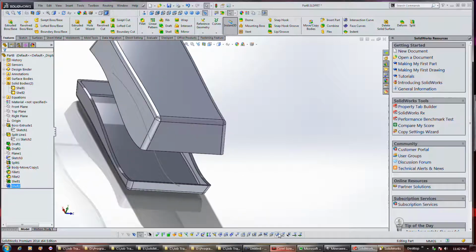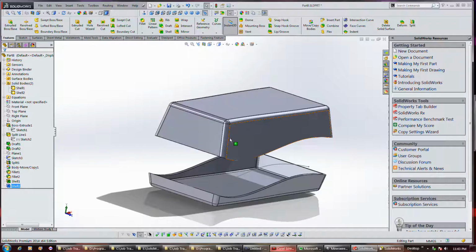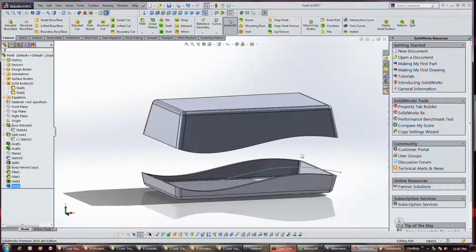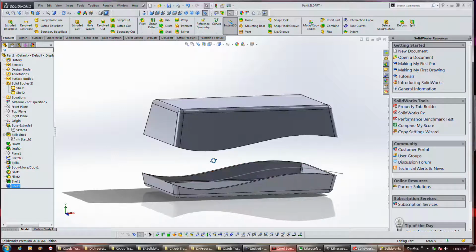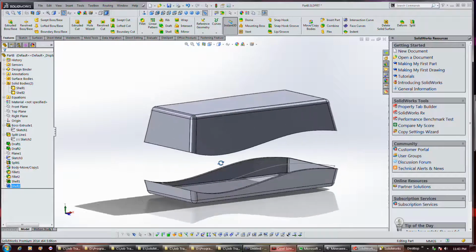Now when it comes to fillets on plastic parts, normally fillets are one of the last things you're supposed to apply on a part you're working on, like for a machine part or whatever. But when it comes to plastics, it's actually critical you apply them early, because you have to put bosses and ribs in it. The more complex your geometry gets, the harder it is to apply fillets to it, because of those relationships that have to be maintained for your DFM rules.